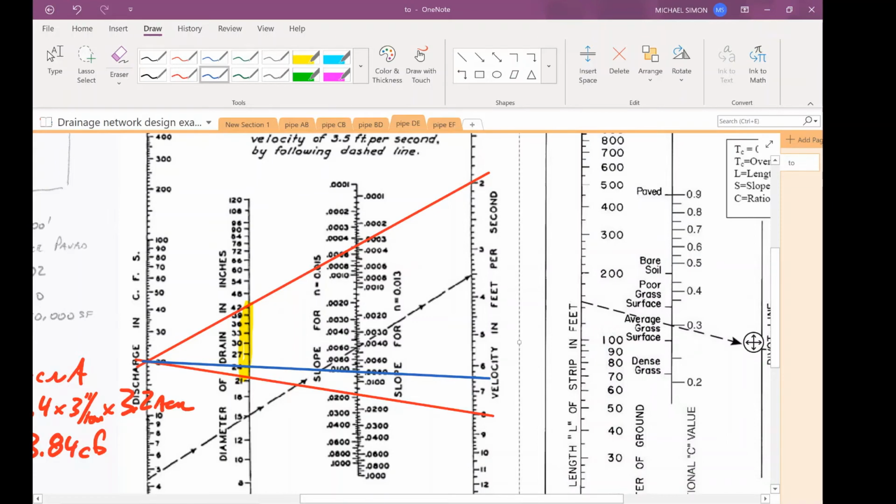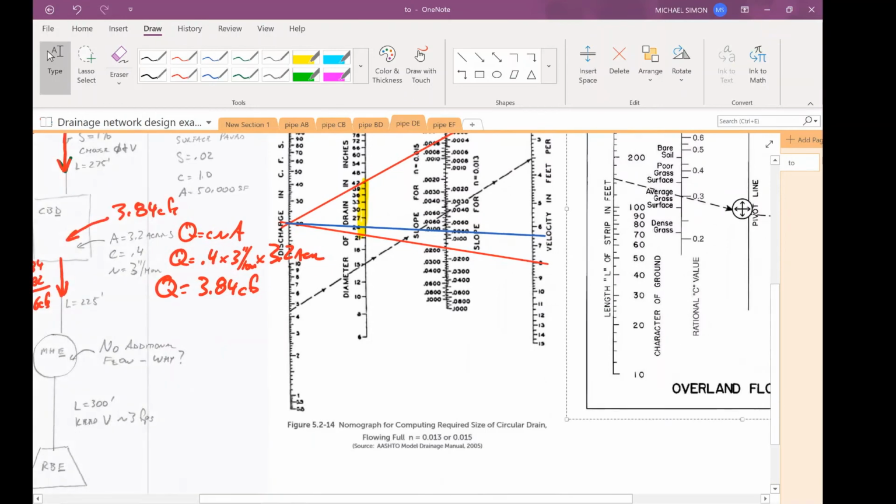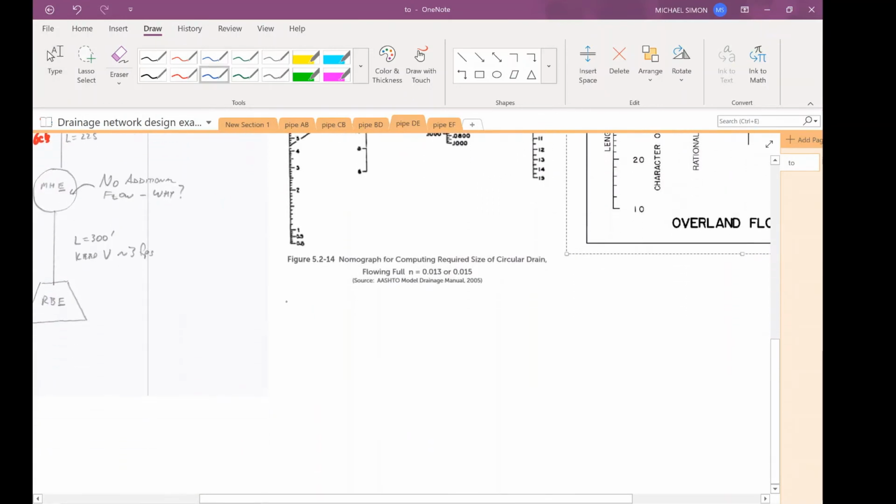I definitely wouldn't go up to like a 36-inch diameter because two things. The water's going to run on the slower side, but 36 inches is a pretty big pipe. That's a big jump in the amount of material that has to get handled and the overall cost to it. So it looks like my slope is 0.0080. So based on that, let's see what we calculate.